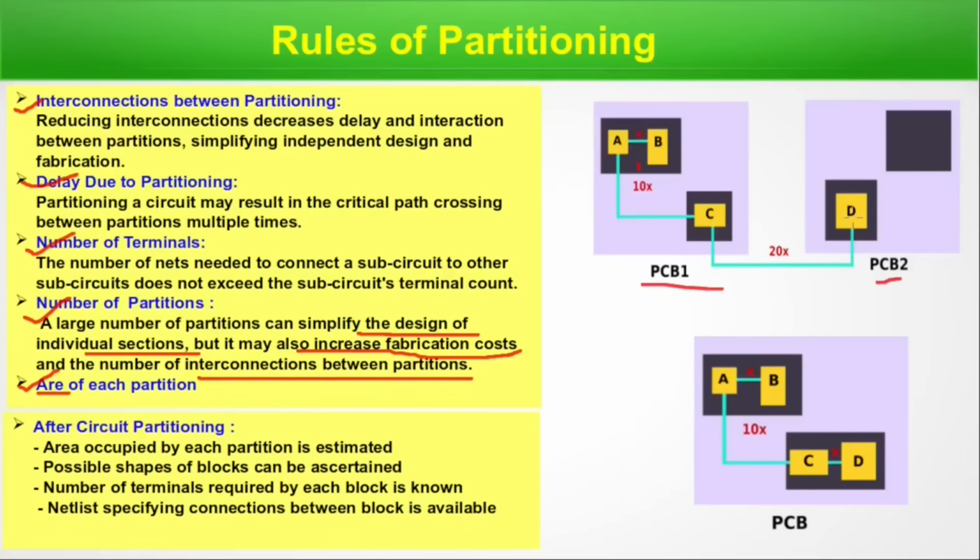Now, if we bring that module within that chip where C is there in another design, so overall that communication time between C and D reduces. So how we place the module depends on their connectivity, their connections and function, how frequently they need to communicate with each other. We have to keep it all in mind. So that way partitioning can be done. It's not that we do it randomly. No, obviously not. Depending on the functioning and depending on interconnections, and because longer interconnection means a lot of time is required, we have to take care of all of these things.